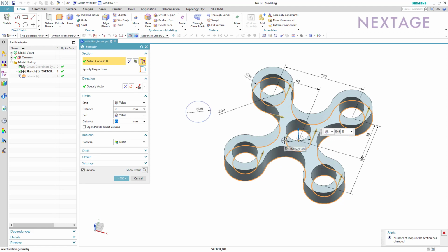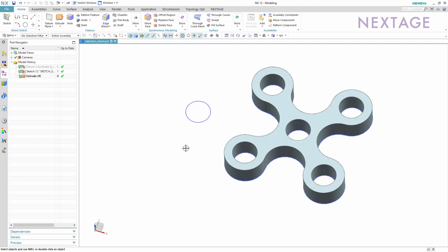So now this curve here is conflicting with the region, or inside the region that I selected, and therefore it will use that curve now in its selection. So if I didn't want it, I could always choose to extrude it as well. The one outside is not associated with any of the selected regions, so therefore nothing will happen to that one.